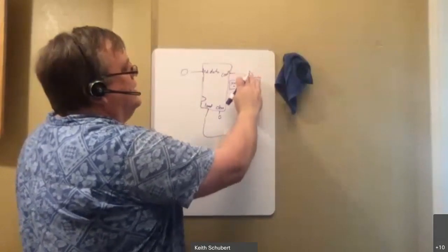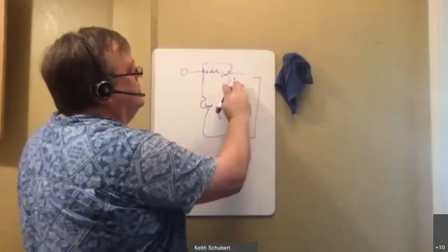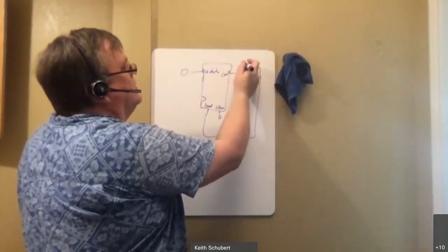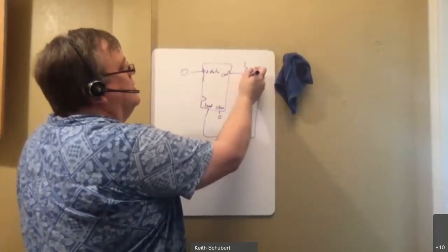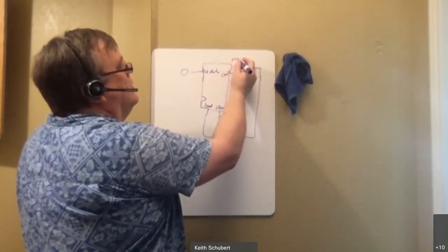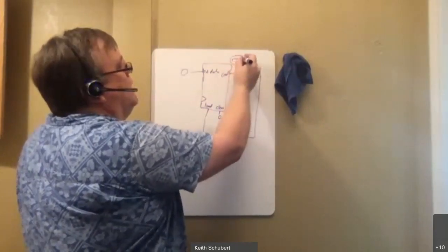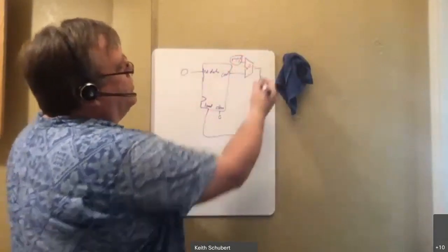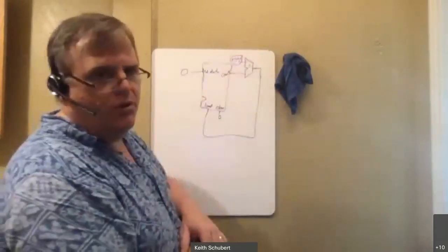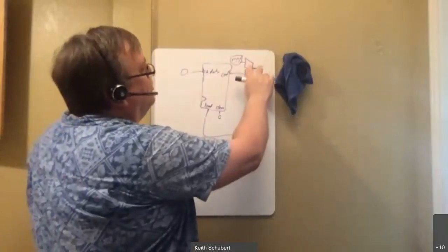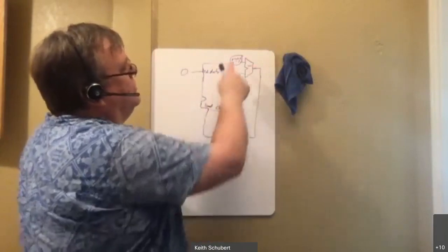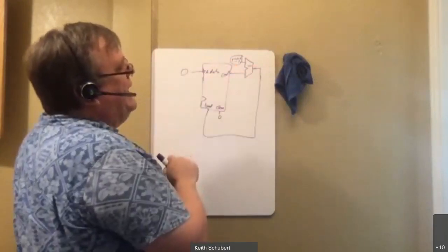But if you slightly alter this circuit, I'll show you why I want to slightly alter this. I can put a different one in here too. So max minus 1, I could still do the equal sign like this. It doesn't matter for checking if they're the same which input you're putting them in. But I could also do this by minus, in which case max minus 1, which is larger, minus my count.